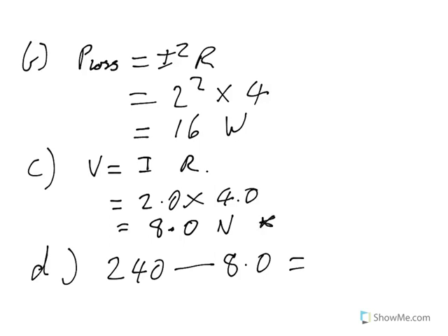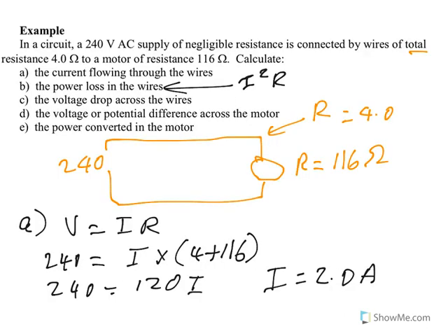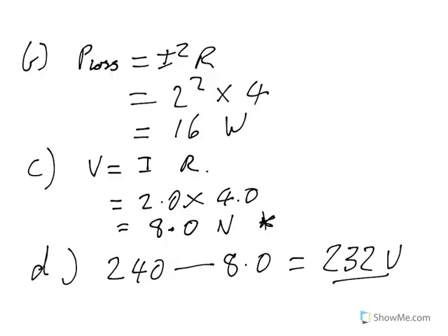That's what we just got. 8 volts used in the wires. So we've got 232 volts left for the motor. So the motor is operating on 232.